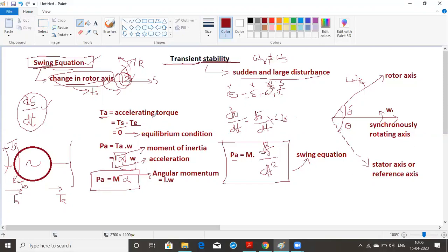That reference bus will have the voltage and delta as known values, and active power and reactive power as the unknown values. Also, a very important concept in a slack bus is that it gives us information about the losses. What are the different types of loss, and what losses are distributed in the complete power system network? We can find out by using the slack bus itself. That is the importance of the slack bus.